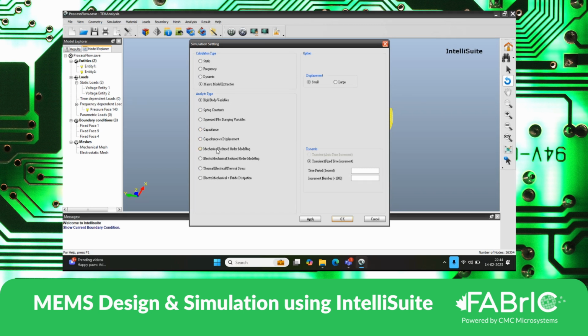So in the process of creating a HDL file to do a system level simulation, we either choose mechanical reduced ordered modeling or electromechanical reduced ordered modeling. In the case of pure mechanical devices like the resonator kind of a device, we generally perform mechanical reduced ordered modeling. In the case of electrostatic force that is applied, we perform electromechanical reduced ordered model simulation.